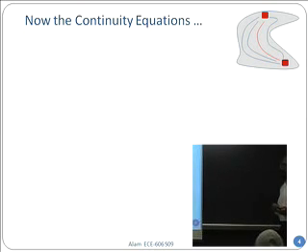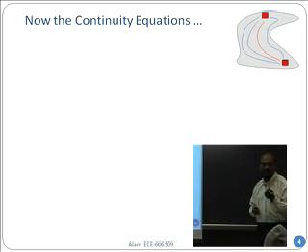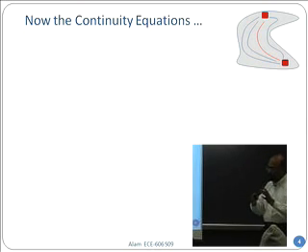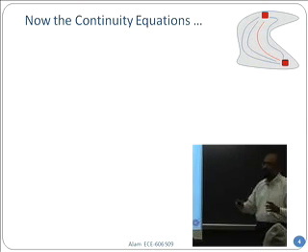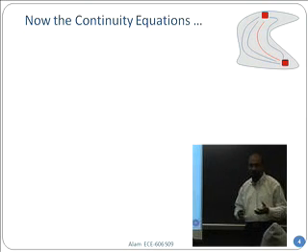Now assume that I have divided this region into many minuscule squares, or in 3 dimensions many minuscule cubes of size a. Now this size is not, of course, atomic size. I'm talking about more like 15 to 30 angstrom, a relatively big region, almost macroscopic in terms of properties. Effective mass is valid, mobility is valid, those concepts are valid, but it is smaller compared to the device dimension.